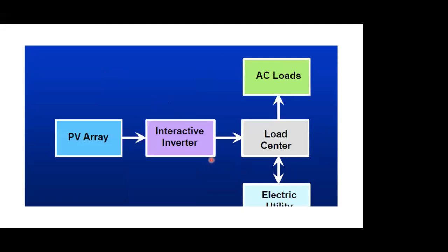However, whenever it comes to be connected into a grid, now you are not the one who is mastering the process. You have to be synchronized with the grid in terms of voltage levels. So for example, I'm going to connect at 380 intermediate voltage or medium voltage. So I have to design that with a three-phase inverter to be 380 volts. You have to connect it with a 50 hertz frequency.